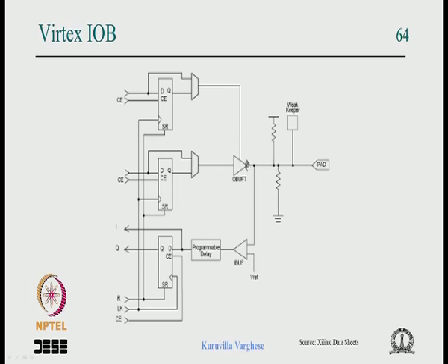We have discussed that if it is tri-stated, this will be in high impedance and it will pick up noise, and if this is an output, whatever is connected at the output, those inputs can start switching, because it can be near the threshold voltage, then a slight noise makes it go up and down around the actual logic level, and the input circuitry can switch and dissipate power. So to avoid that, you can pull up, pull down, and there is also a hold circuit or a weak keeper which remembers the last value.